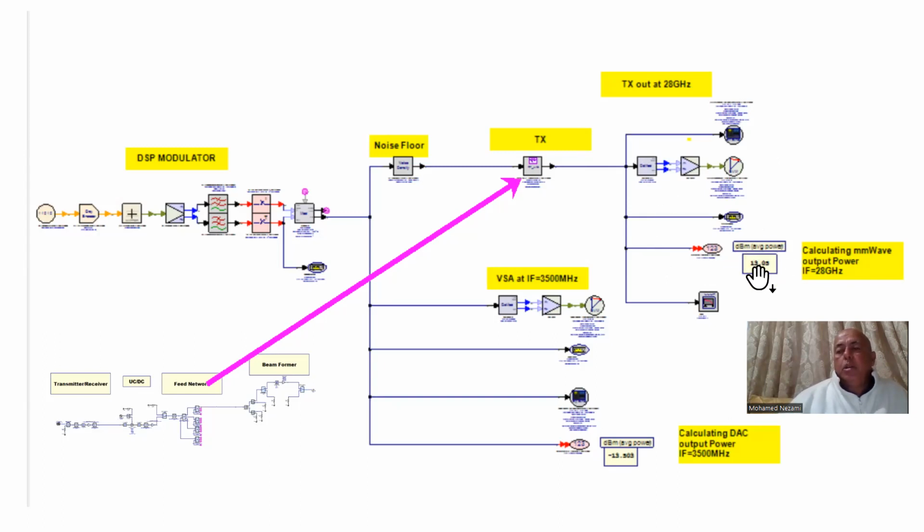In this case, you can see the number in here when I grab this. It's 13 dBm, and that's really what we want. We want this signal to be 13 dBm, because that's what we designed the system for. It is minus 16 here, and that's this point here. Of course, I have almost the same thing for the DAC output, for the power spectral density. So you calculate the power in here, it's minus 13 dBm, okay?